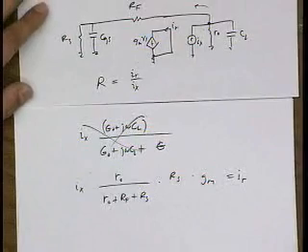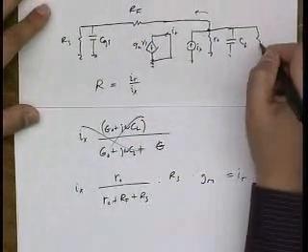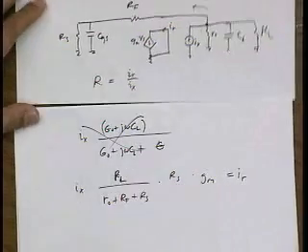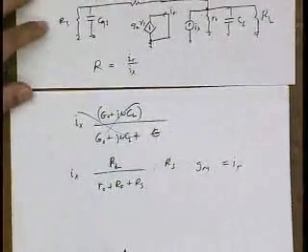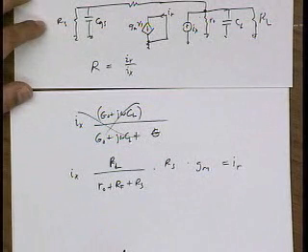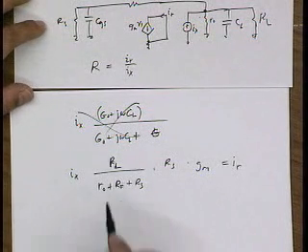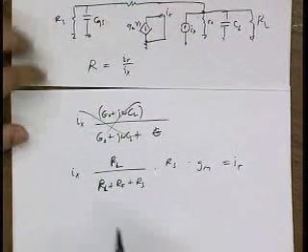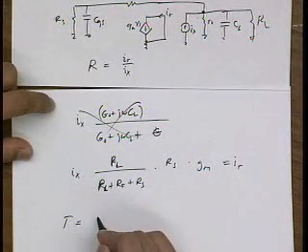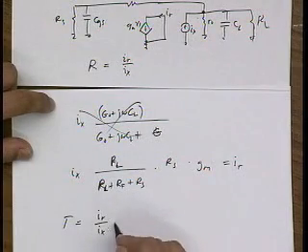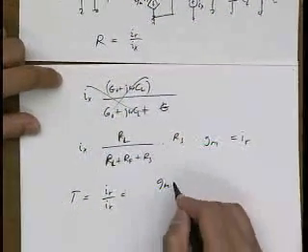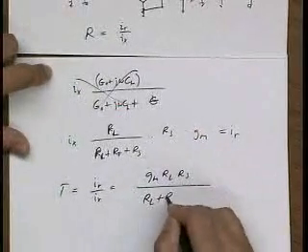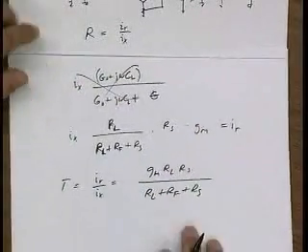Is that right? And let's say I have an RL here. Just to be consistent with our previous calculation, RL dominates the output impedance. So then the loop gain, which is IR over IX, is GM RL RS divided by RL plus RF plus RS.